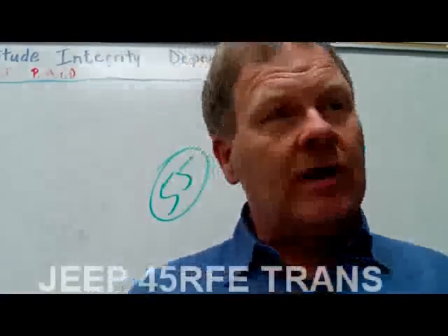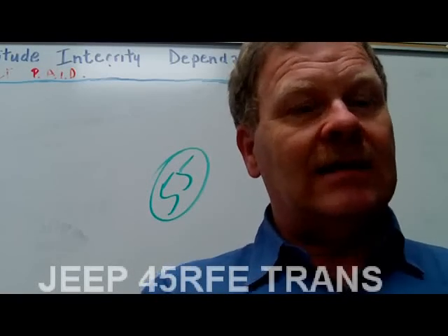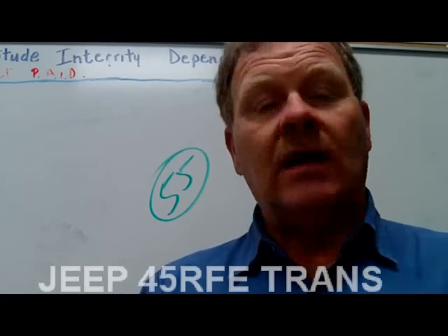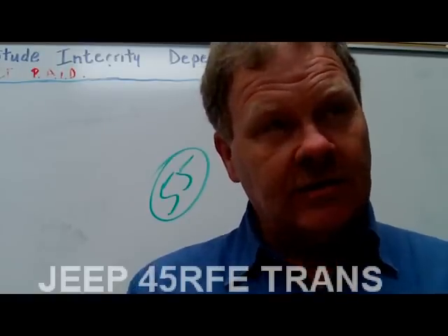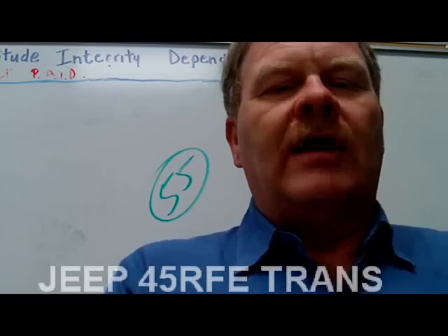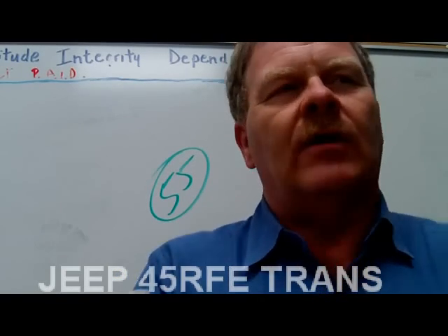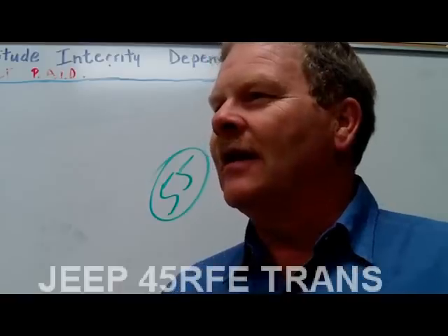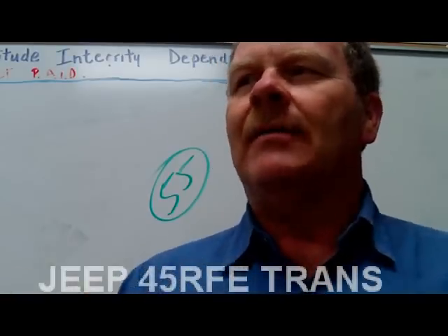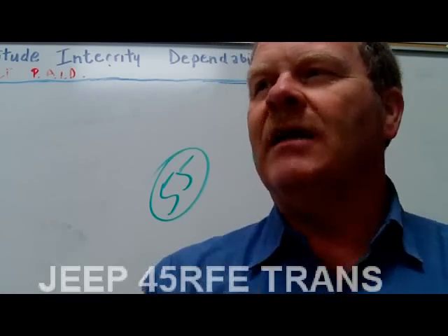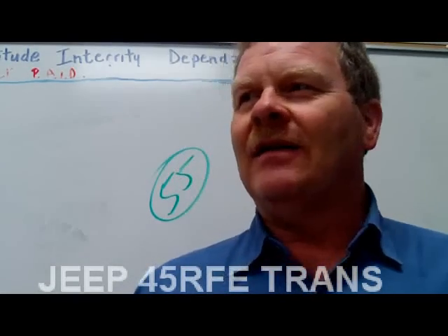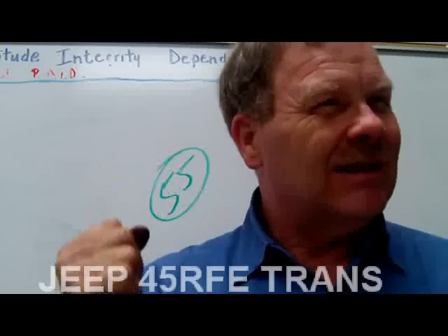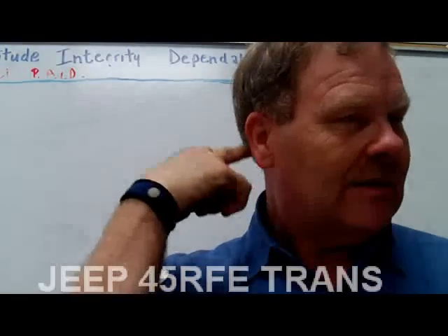And if it's squeaky clean and somebody knows just how to stack it back together and they look at every part, you're not going to have any trouble when you go back together with it. If you watch somebody do transmissions who really knows what they're doing, you'll see them rattle it around and stick it down in there, and they say, well, that don't really feel right, and then pull it back out. It's not about cramming it back together the best way you can so that you can beat the pump into it. You know what I mean? And you ought to be able to grab that turbine shaft and turn it when you're done. That's just the way it is.